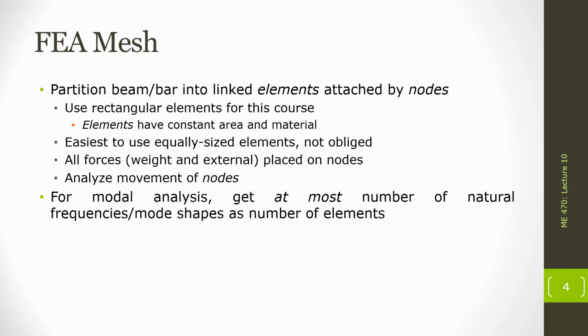But we're going to have the issue to worry about that when we go from a continuous system to this multi-degree of freedom system, remembering back to Unit 2, we only can find as many natural frequencies as degrees of freedom of our problem. So if we make too coarse a mesh, not using that many elements, not creating that many nodes, we're not going to be able to even find many of the natural frequencies. If we use a finer mesh using more elements, more nodes, then we're introducing more degrees of freedom into our system, and we're going to be able to then find more natural frequencies, more mode shapes of our system.